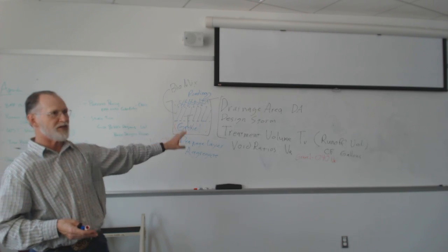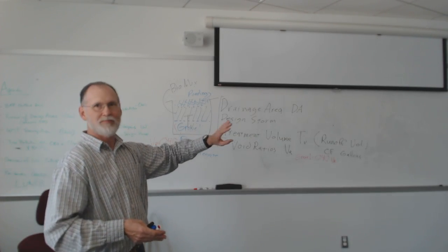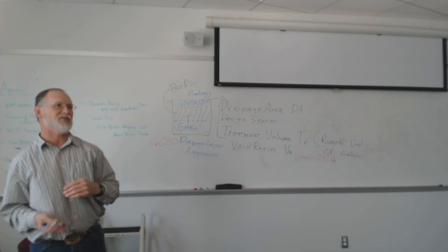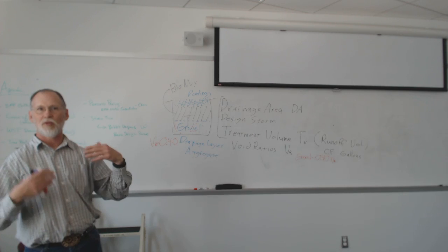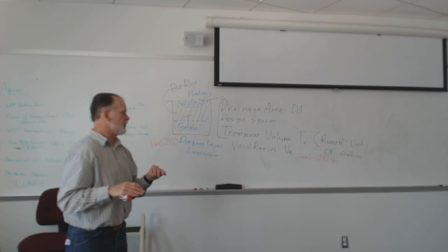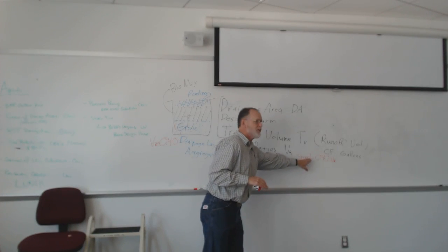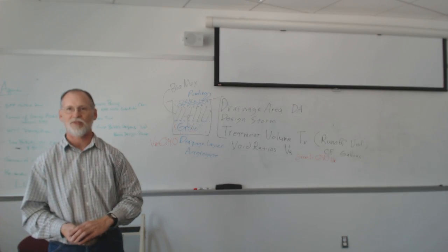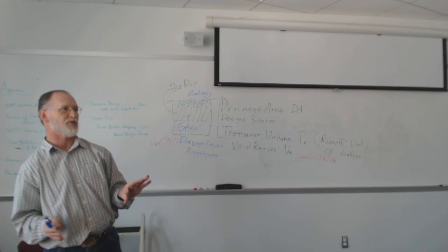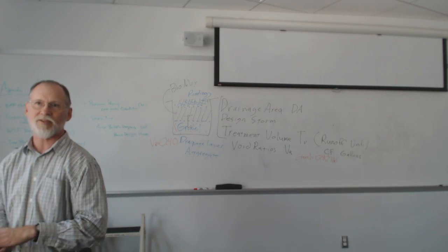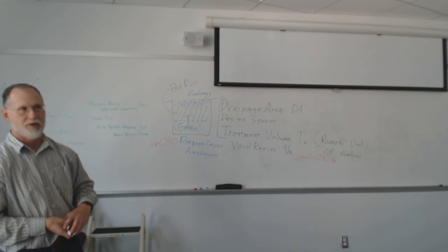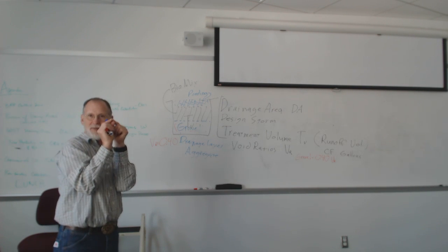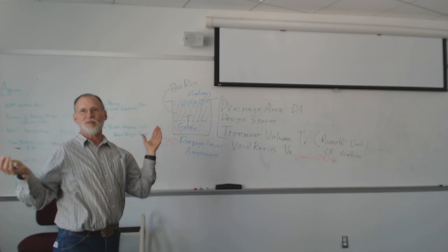I assume some graduate student at some Polytechnic University has proven this, and there's probably slight variations, but for the purposes of this class, it has been carved into a tablet near a burning bush that the void ratio for gravel areas is 40%. In the regulations, they do not differentiate, so I'm assuming it's pretty darn close no matter what kind of stone you use. Okay? But when you think about little bitty stones, you have thousands or millions of little bitty voids,